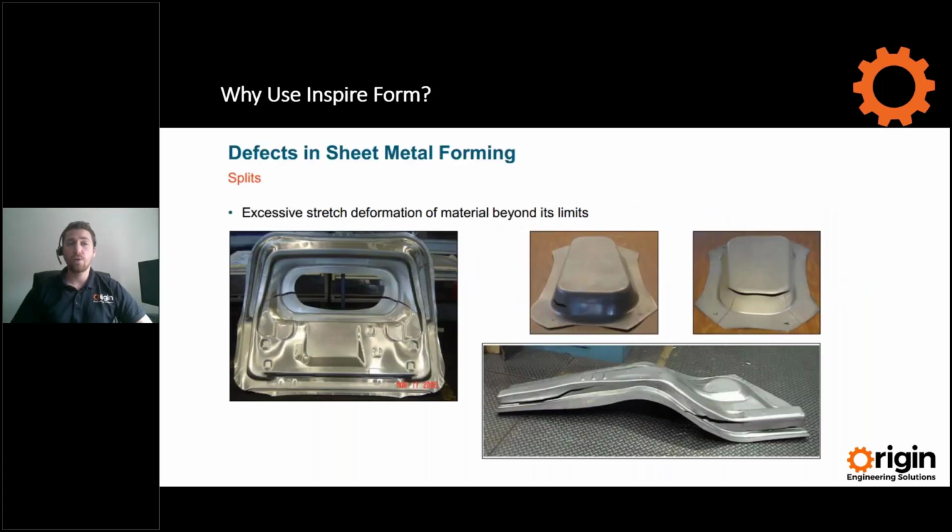So why use Inspire Form? Rob's briefly touched on this. One of the main reasons to use simulation in general is to hopefully predict defects before manufacture. The last thing you want to do is manufacture expensive dies or tools, and then you're forming your parts and you find that you're getting big errors such as splits, so the parts are no good.